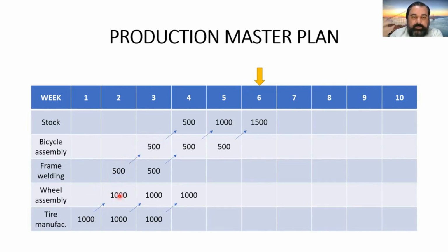You cannot work faster than your previous processes. So if the bottleneck is right here at the first process, then all other processes will work with lower efficiency. They will operate 50% of the time, or with 50% capacity.